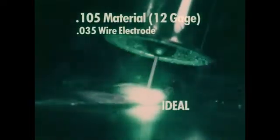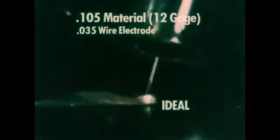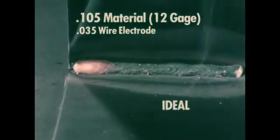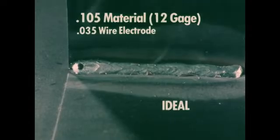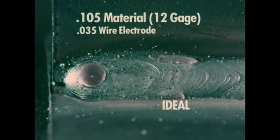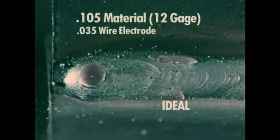There is minimum spatter. The arc sound is steady and smooth, almost like bacon sizzling. Areas on either side of the weld joint are free of spatter. The weld bead is the proper width. The crown or top of the bead is not overly high, which suggests that good penetration has been achieved. The operator has successfully found the right amperage or wire feed speed to use.